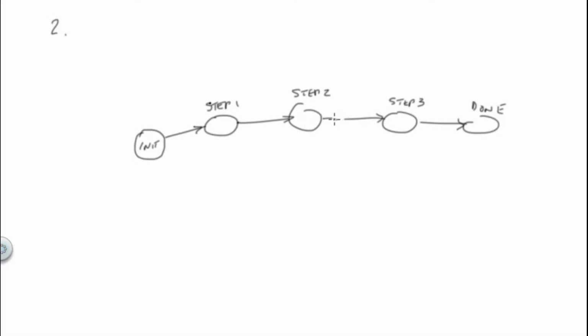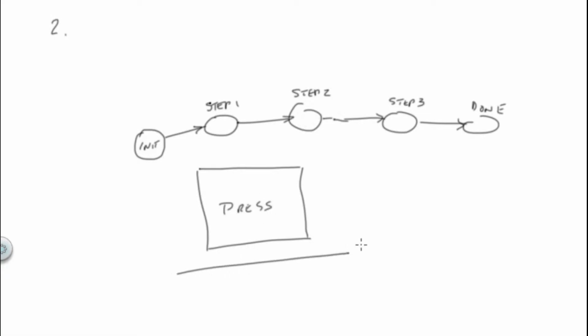Because for what it's worth, I was working on a press. It was a pneumatic press, and this would be the visual of the press. It was a hood liner press, and here was a light curtain. Okay, so we had a light curtain, and here are my buttons that I pushed to say start. So I pushed these 2 buttons, and this press came down. Now I was going to look at something in here, and I wanted to check it out, so I walked into the light curtain, and it stopped the press.